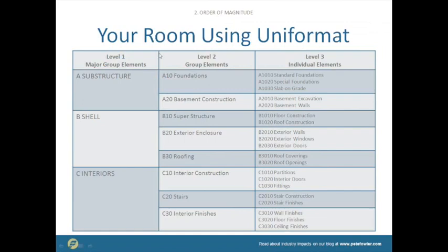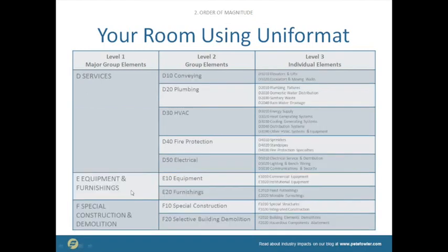So the question is, we don't have time to do this. We used to do this program as a 2-hour program, and we'd have you print out the estimate sheets, and we'd break down. But we usually like to outline our estimates using Uniformat. It's a way to organize building elements. So foundations, any substructure issues, A, and then you break it down to, we usually work at level 3 for building elements. But then in the shell, so the shell is the exterior cladding and the windows and the roof, and the interiors are stairs and finishes and walls and floors and ceiling finishes.